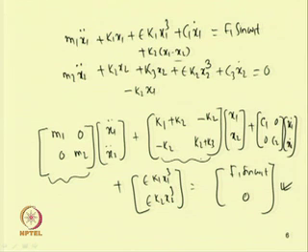We can write this equation, or at least the linear part, in an uncoupled form by using the modal analysis method. That means we can find the dynamic matrix A equal to M inverse K. If you write A equal to M inverse K and find the eigenvalues and eigenvectors of this, then we can write the modal matrix.